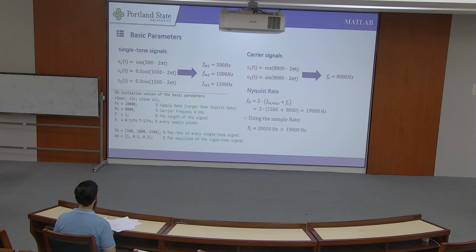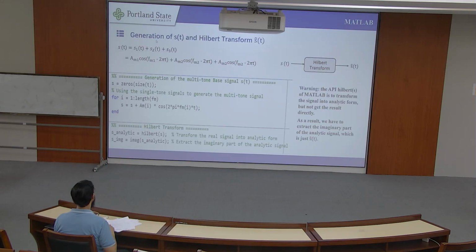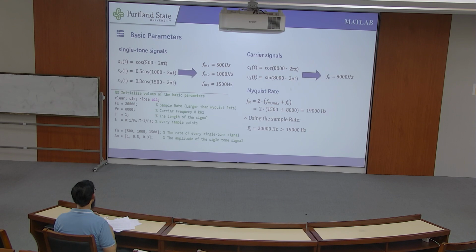Next is the core equation in the middle. The first one, s(t) = m(t)cos(2πf_ct), is our original message signal multiplied by a cosine carrier. This is exactly how standard modulation works. The next part is ŝ(t)sin(2πf_ct).